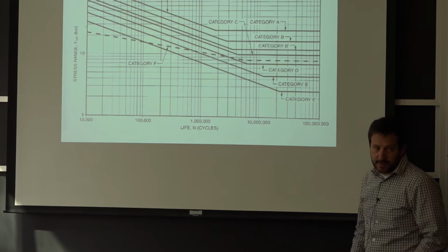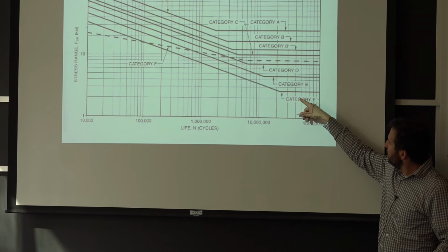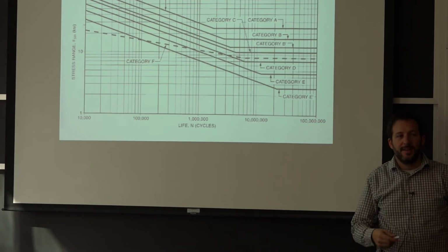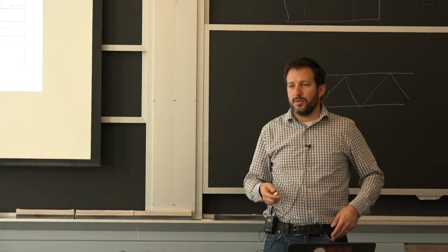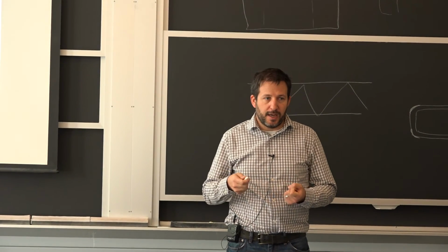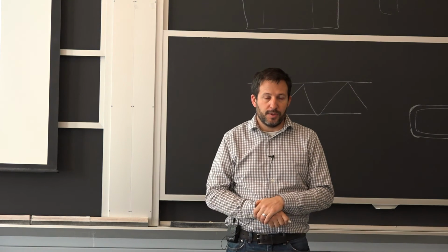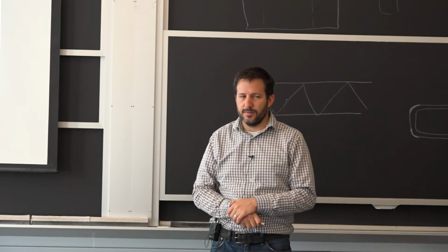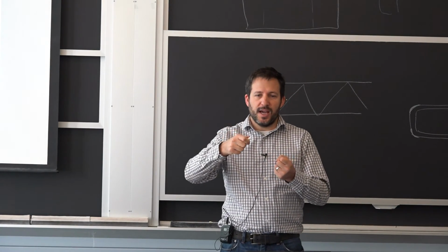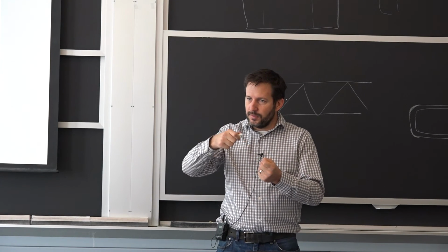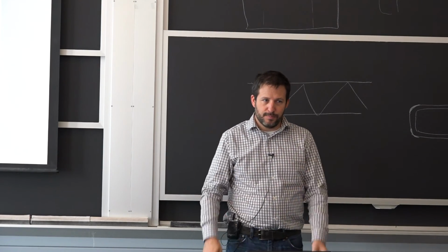steel weld, that is essentially a transverse weld, just like that, a fillet weld. So a fillet weld here gives you this level of between 2 and 3 KSI, so 10 times less than the yield strength of the base material is what you can have for cyclic load. And I cannot emphasize, though, that if you're going to load it only once, you can go to much higher. It will typically be about 60, 70% of the yield strength of the base material. And what happens when you do that, though, is you'll have a little bit of yielding of that surface that is in residual tension. So your dimensions can change a little bit. It's just part of that process.